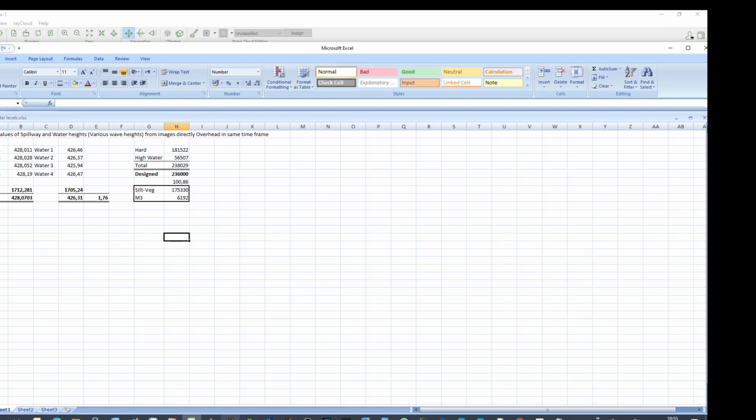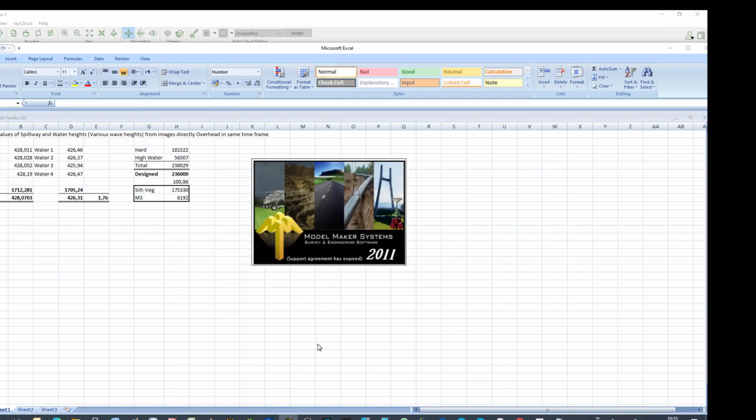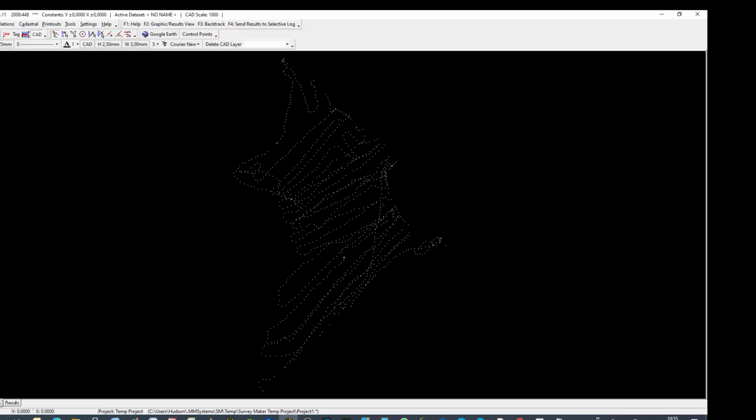From this we took the data into, first of all, the bathymetric data. We converted from WGS 84 latitude and longitude. Now the sounding is what you get in the CSV from the sonar device.